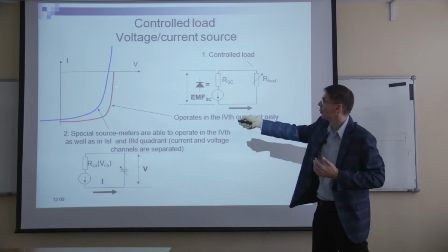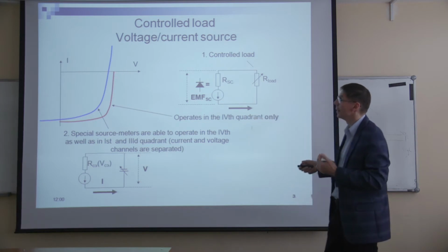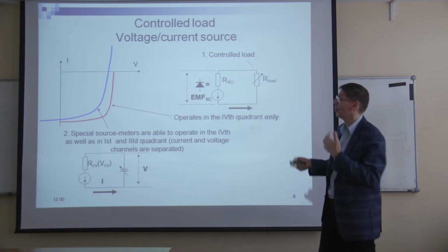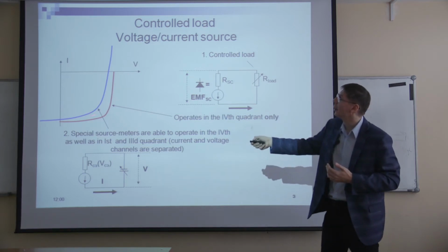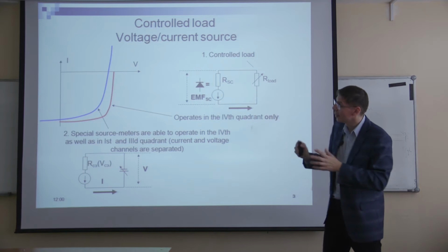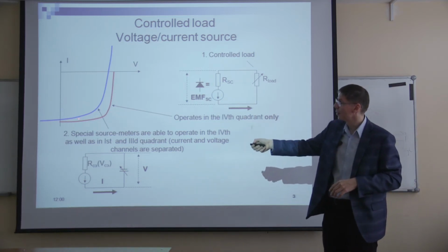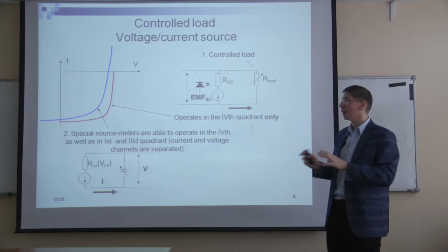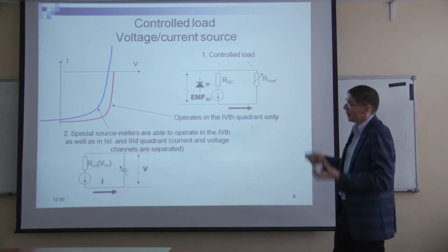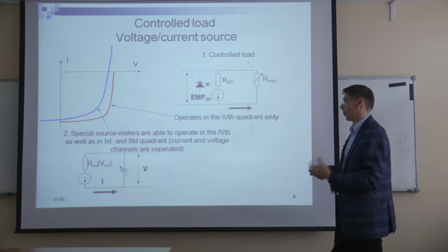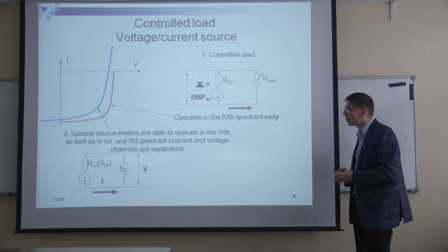I mean, if you have some strange behavior just near the VOC, sometimes you may be required to go further. And the same if you have something here which is maybe not normal behavior, like some kind of knee of the IV curve, in this case it's quite important to go further to the reverse bias.